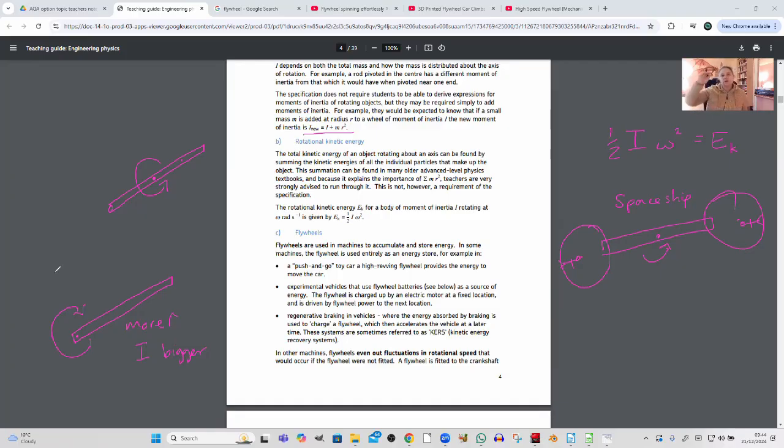If you have your gravitational potential energy at the top of your ramp, and you want gravitational potential to equal kinetic energy at the bottom of the ramp, then it only works if you don't rotate anything. So rotating your can of beans means that the linear kinetic energy of your can of beans is not going to be the same at the bottom of the ramp.